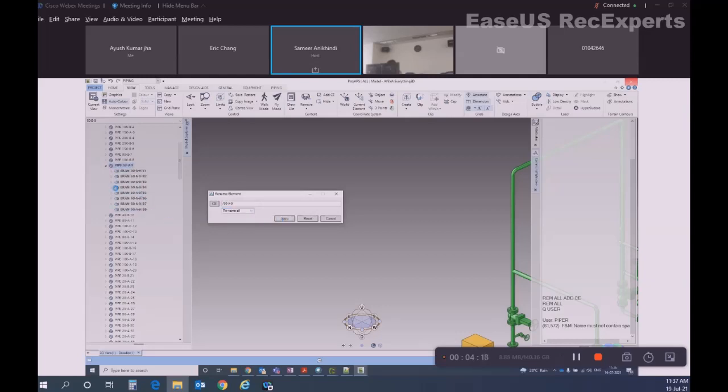Apply. So see, even this one was B9 earlier, it becomes A9 and so on. But if I just use rename only, it will just rename this particular element. It will not change the hierarchy below. It is also not changing the reference number. The reference number is still the same, because the reference number is the unique identification of that element in the hierarchy.